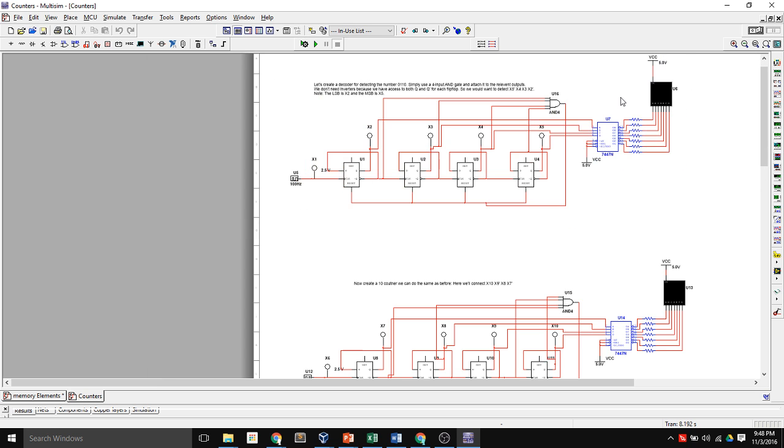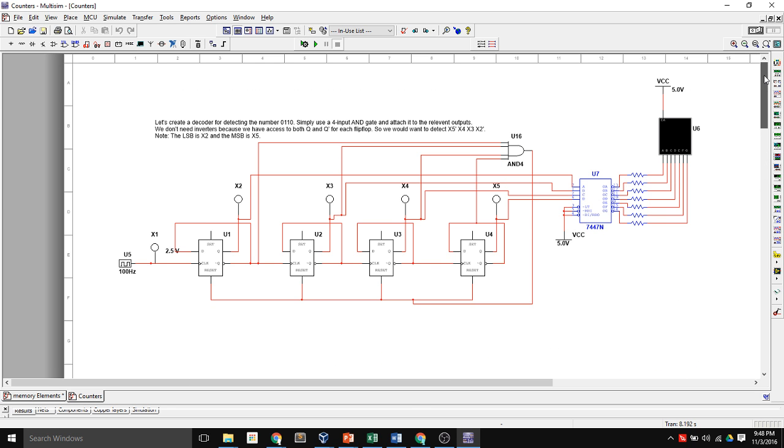So in this top circuit that I'm trying to zoom in on, what I'm doing is I am using these outputs of Q and Q naught for each one of these bits as the counter here that will create these values. I'm going to take those values into a NAND gate and then take that gate output to trigger my reset on my flip-flop.